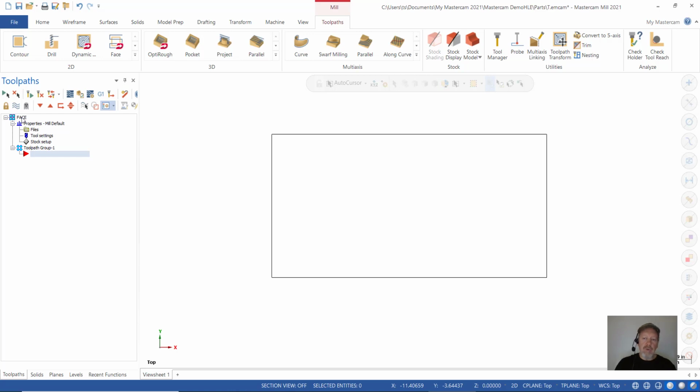In the future, if you're creating an operation that is operation 1 or for side 1, then you can change the name of that machine group, and that will help you identify what that machine group is going to do for you. You can create multiple machine groups in this one file, so you want to be able to label them correctly.